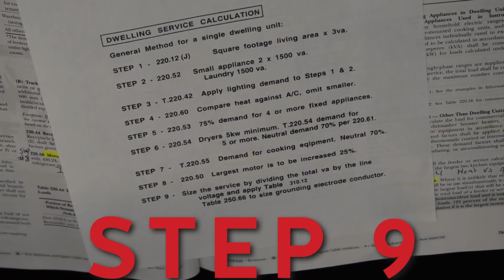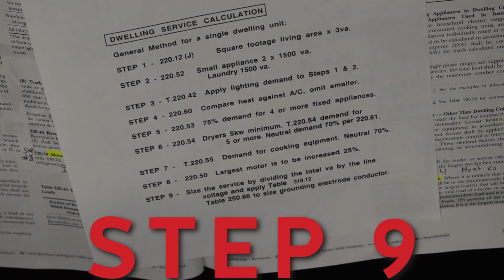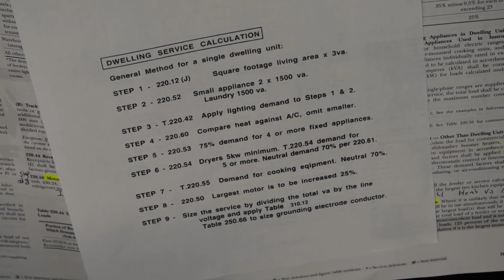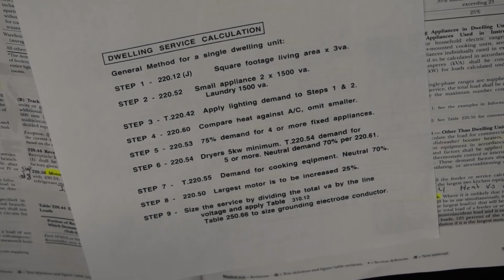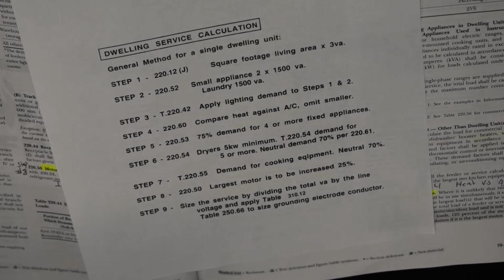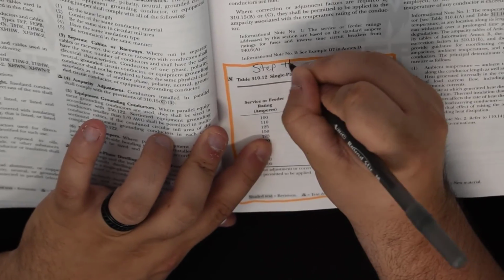Now to our last step, which kind of throws all this together, comes up with a sum, and we figure out the size of the service required. It does take us around a couple different places. It says size the service by dividing the total VA. That's all steps 1 through 8. Add them up, come up with total VA and divide it by the voltage, and then apply 310.12 table. So let's go to 310.12 table, and we'll label that step number 9.